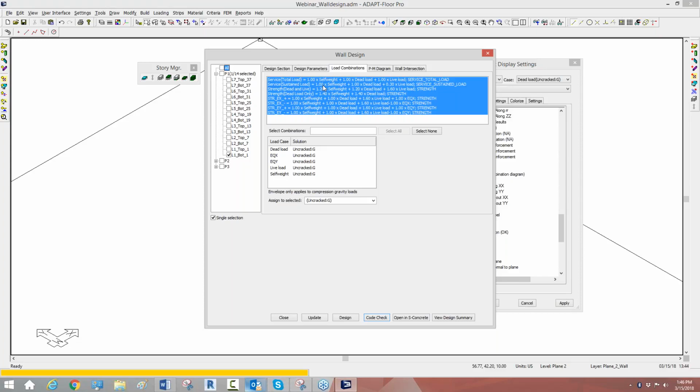solutions that are available. So if I was to have set up this model using usage cases 1, 2, 3, 4, 5, and I ran all 5 usage cases, which are basically just stiffness profiles, the program would store those 5 usage cases, and I would have the ability then to select which solution I want to use for compiling the reactions necessary to design for these combinations.